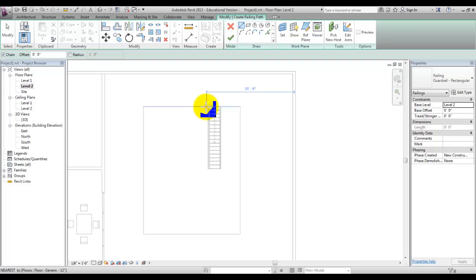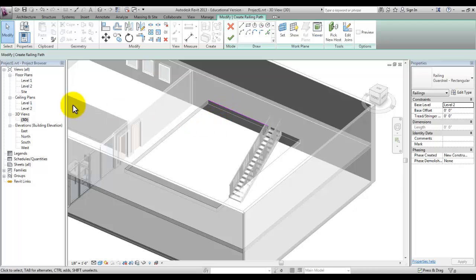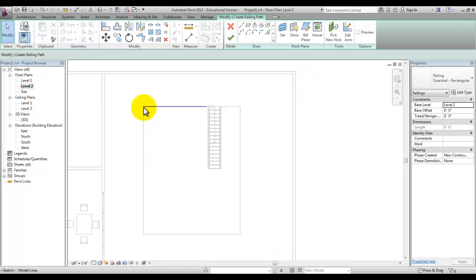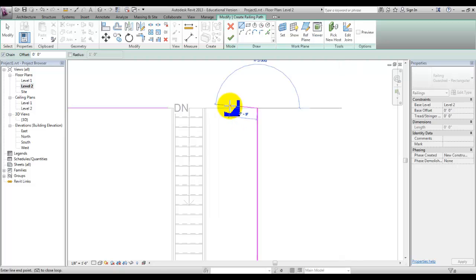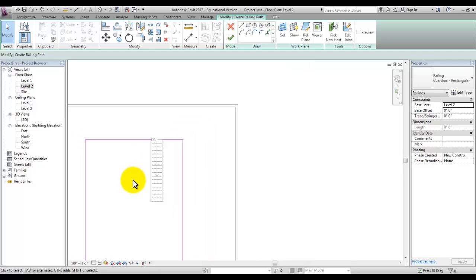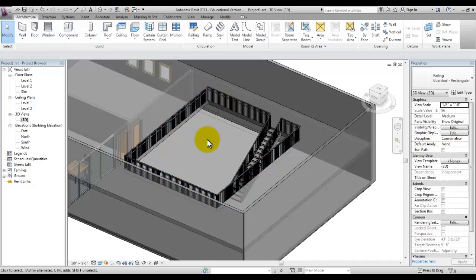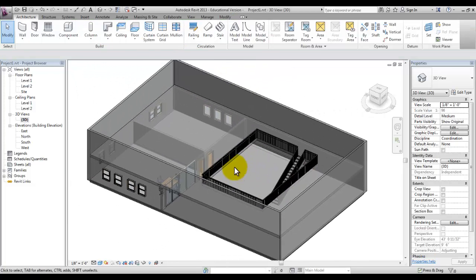We're going to use the line tool in the draw area there to draw here that magenta sketch again at the edge. I went to the 3D view just to make sure that the points that I was picking were along that correct edge. Here, I can also select the magenta line and stretch it over to line it up with the other rail. Check it in the 3D view, make sure that the magenta line is in the correct location, and then pick the green check mark.